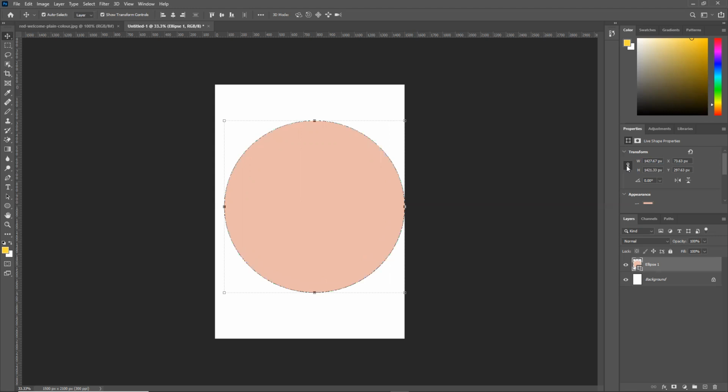But immediately I turn it off, if I'm increasing this, only the width will be increased and will not affect the height. See that only the height is reducing. And if I come to the width, only the width is reducing. But immediately I link them, if I increase the width, automatically the height also increases.